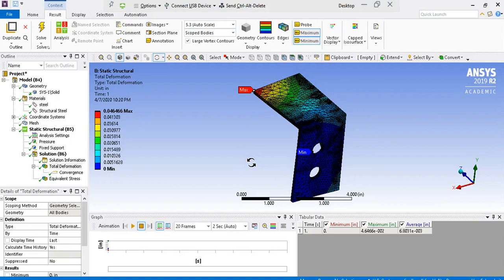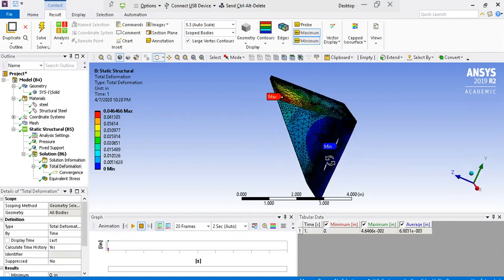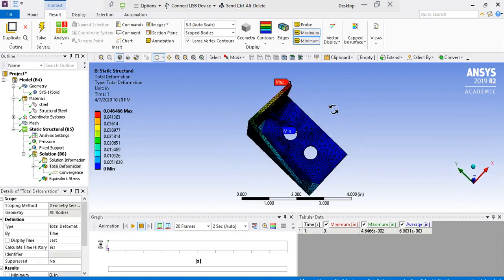The thing is, you are verifying these FE results against the analytical solution, the exact solution using your mechanics of materials equations. If a force is applied on a structure, how can you calculate the deformation? Based on the moment, the torsion, and the stresses, you can calculate that. So you are verifying the analytical solution against the FE solution. That's how you do the hand calculation. Okay, so this example shows how to do a convergence plot. Next, I will do a steady state thermal problem in the next clip.